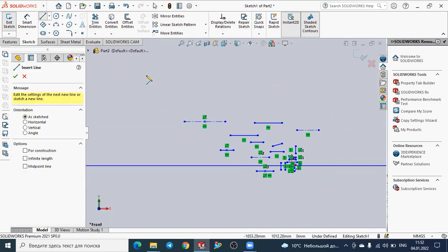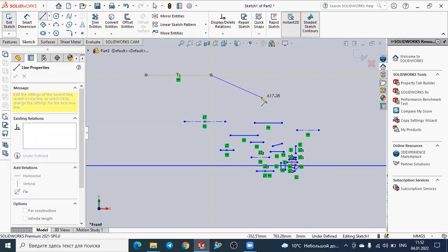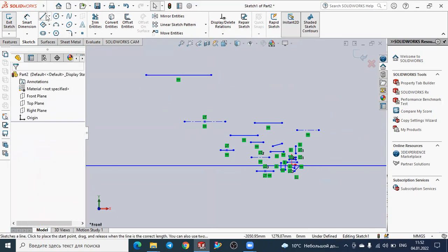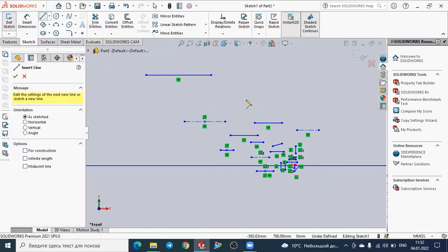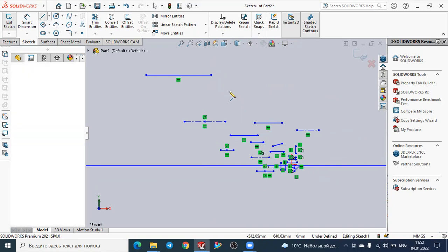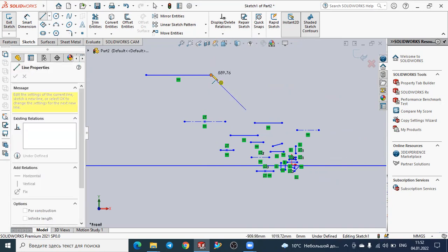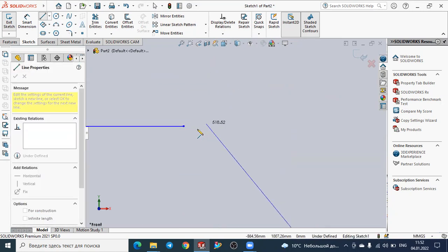Now see here, let's select the line again, and see here one horizontal line, and if you want to add any line to this one, for example, just click here, and if you bring your mouse to this point, you see this yellow circle is created, it is again the helping line, which means that these two, the horizontal line and inclined line, intersect at one point.